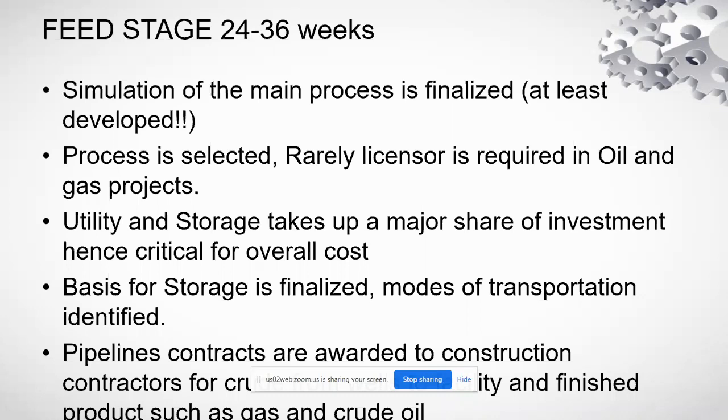If the aim of the facility is to generate LPG or propane gas, which is then injected into national grids or networks, then gas storage is also involved. The basis for storage is finalized again in this phase. By basis, I mean the number of days of storage and the types of tanks, depending on what type of crude is handled, its vapor pressure and its properties.